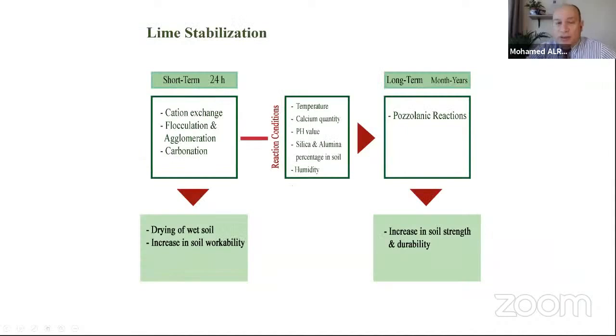This is the equation of how lime stabilization reacts with the clay minerals, and it passes through two stages. The first one, which I call the short term, is the carbonation, flocculation, and agglomeration. Then we have the most important reaction, which takes a long time to occur.